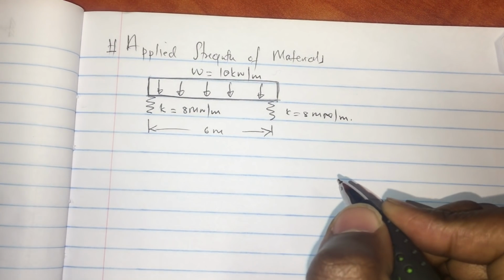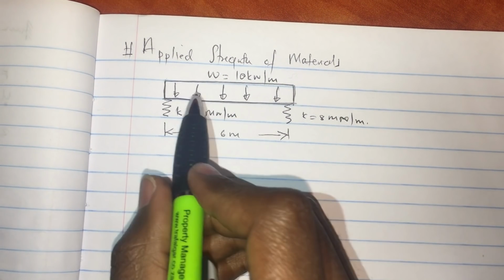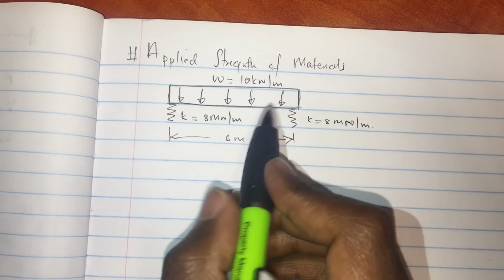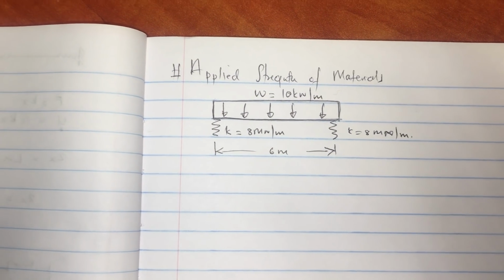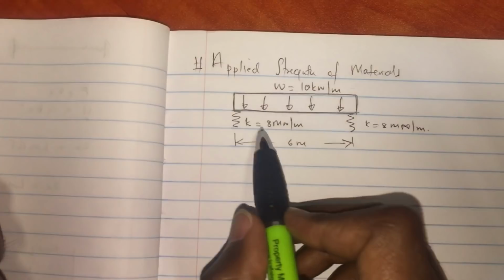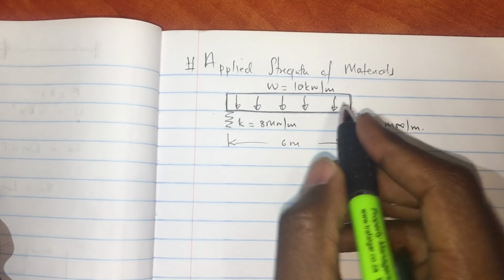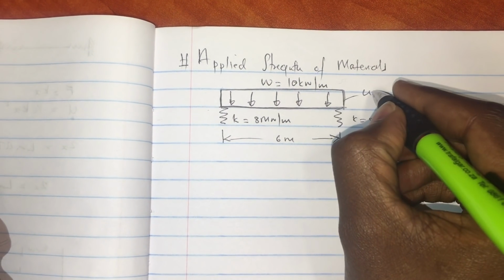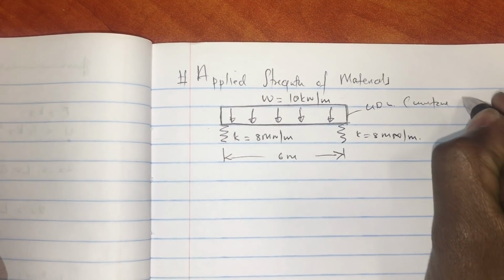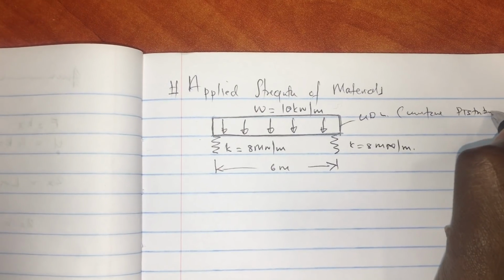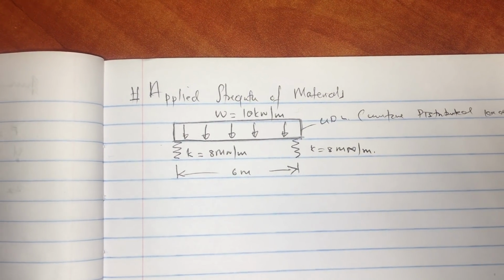In this session, we're discussing strain energy. Strain energy within a system like this, where we have a uniform load simply supported by two springs. In order to solve a situation like this, you divide the system into two sections. One section involves the UDL, the uniformly distributed load, and the other is the springs themselves.